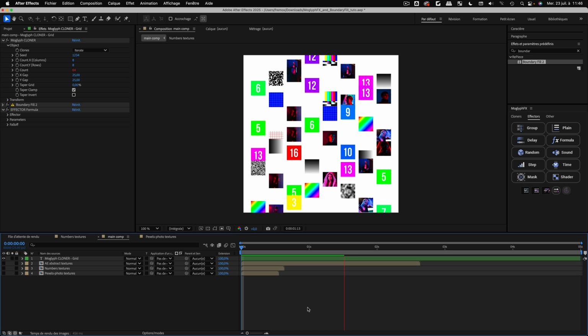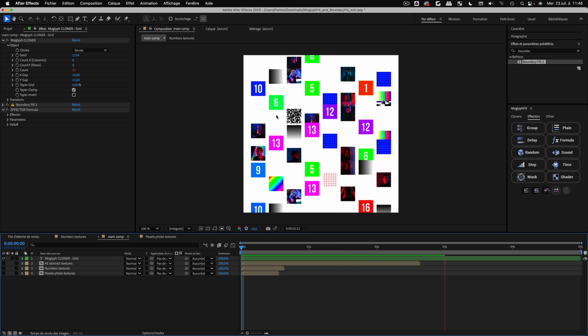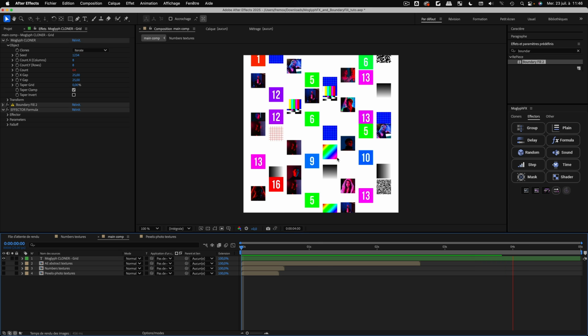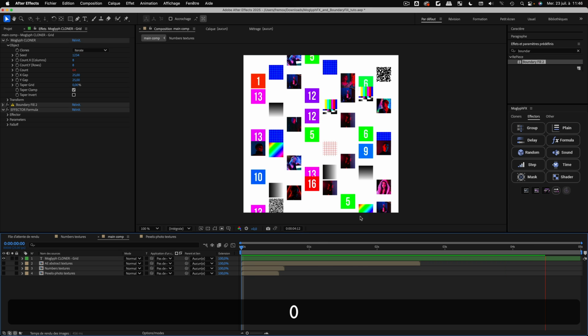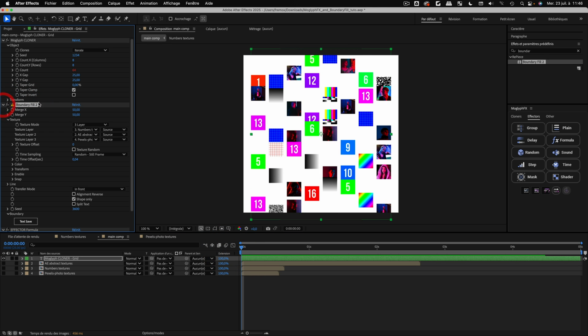And there are some issues where the textures change and randomly change, and this is because the BoundaryFill plugin considers some of the clones as the same entity if they are overlapping. So be sure to not have groups of clones overlapping each other too much.